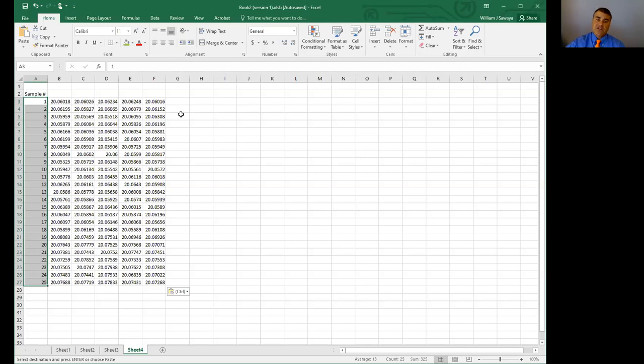Now, the first part we've already decided, right? We decided which dimension we're going to measure. I showed you that on the engineering drawing. The next step is we decide how often we're going to sample and how many measurements we're going to take, which is usually a function of time and cost. So I already decided that we're going to collect samples of size 5, and I've got my first 25 samples. I believe the process is relatively stable, so we're going to go ahead and do this.